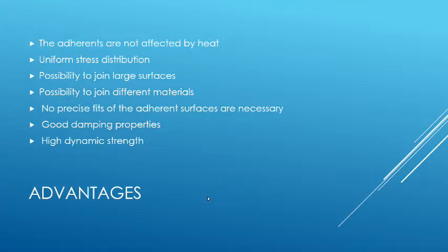Since the operating temperature is low, the material structure of the adherents to be joined is not macroscopically affected, and the deformation or internal stress, which are generally related to the application of heat, rarely occurs. It can be said that it can be bonded without any heat supply.